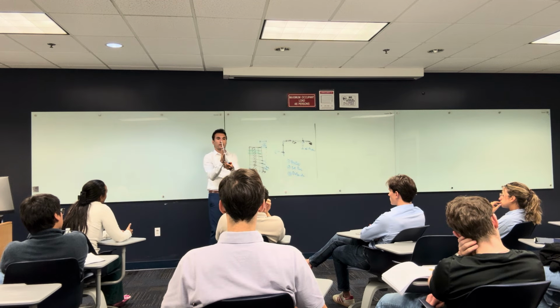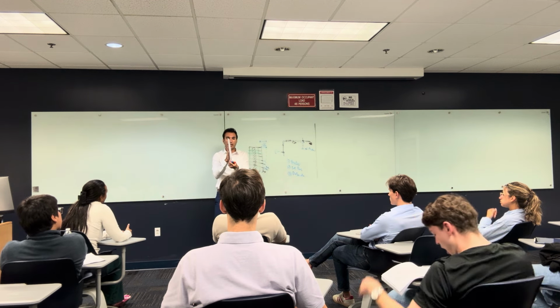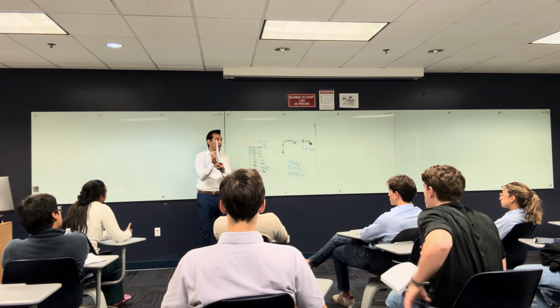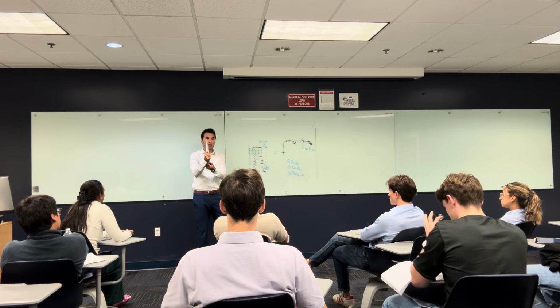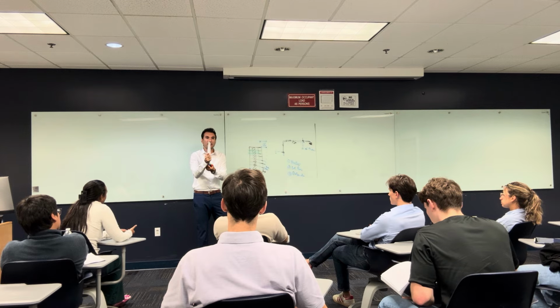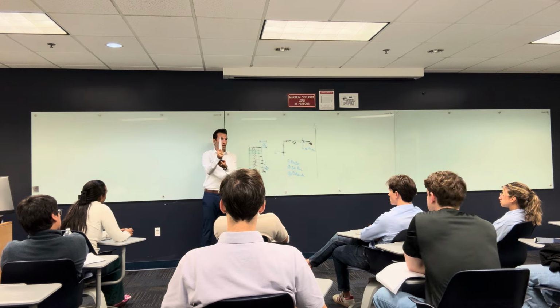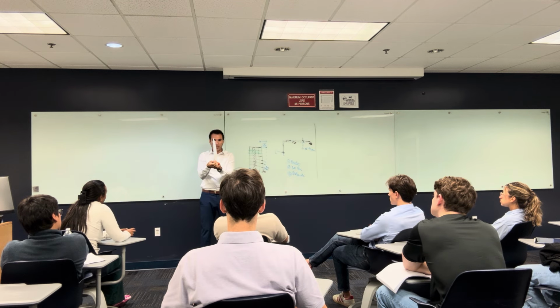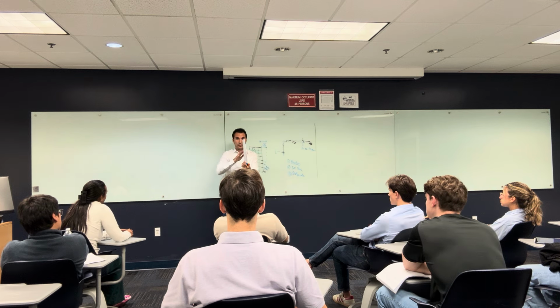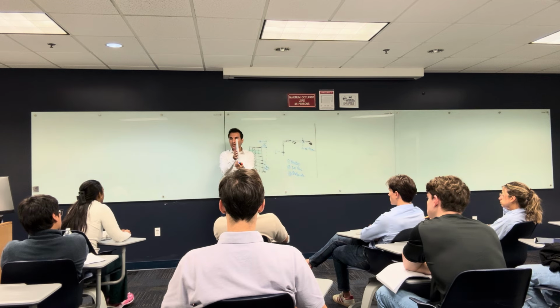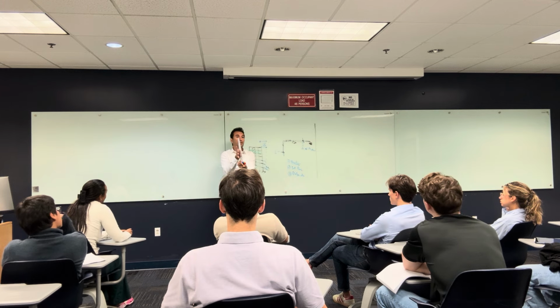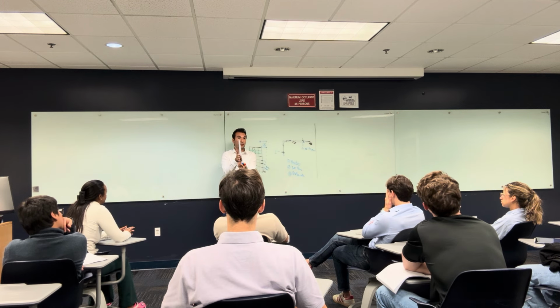And the one that resists the lateral load is the stiffness of the column, right? If this column is really, really stiff, like let's say the stiffness is infinity, this thing is not going to move. It's going to stay the way it is. If I shake the ground like this, the ground is moving and my structure is moving like this. This is never going to happen, but let's say it did, this structure would not have any internal forces. If your structure has all the deformation as translation, there are no internal forces generated in the structural system.